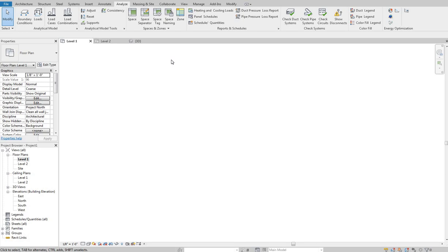Analyze. This is where you analyze heating energy, different configurations of building form and shape and that sort of stuff. They're getting better. I don't know that I would use these for your LEED analysis or anything like that. It's great for initial ideas. So maybe you throw a massing in here and you rotate it 10 degrees this way, 10 degrees that way. How does that impact the energy performance of the building? It'll give you a rough idea of whether one configuration is a little bit better than another, but I wouldn't take those numbers as gospel or anything like that.